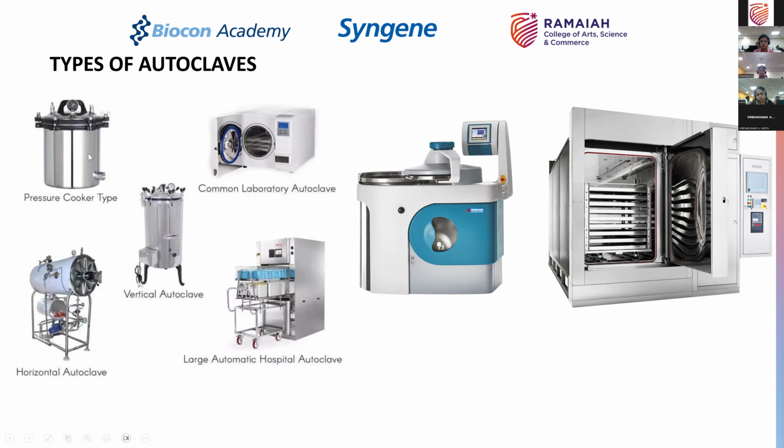Okay. So you have these smaller ones, pressure cooker type, in small clinics, small medical centers, or even in laboratories. When you are dealing with a very small quantum of components, you can use a pressure cooker type autoclave. Water is filled, components are placed inside it, and it is sealed.